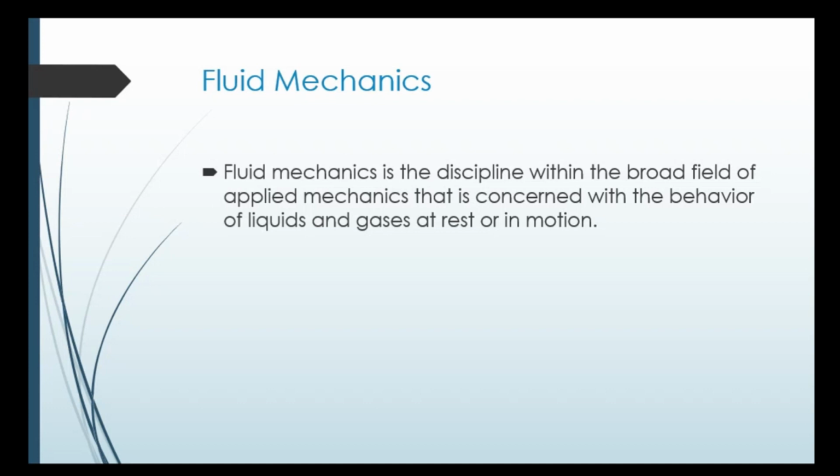So if I put water on this surface, and if this surface is not moving, the velocity of the bottom layer of the water would be 0. And if I pile up a chunk of water on that, imagine there are transparent walls, and I start moving the upper layer, let's say I move this remote on that top layer, then the top layer would bear the velocity of this remote. So this is basically called the no slip condition. The top layer or the bottom layer of the fluid sticks to the surface of the body in motion or at rest. Okay, this is the no slip condition.